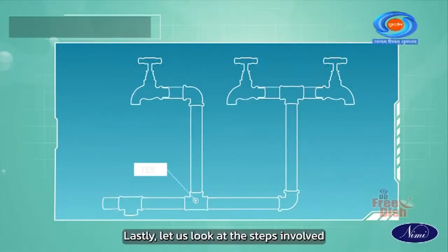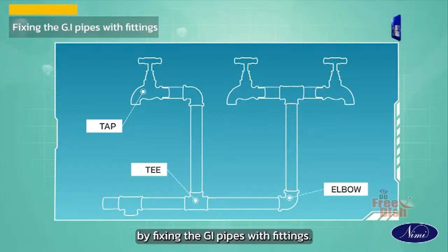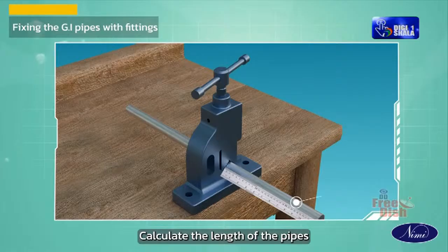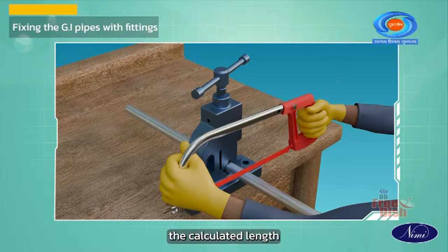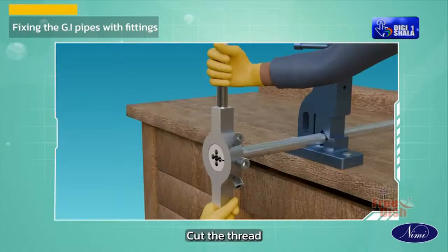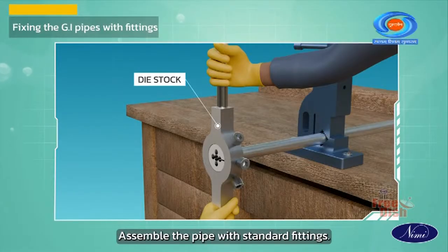Lastly, let us look at the steps involved in a simple pipeline connection by fixing the GI pipes with fittings as per the drawing. Calculate the length of the pipes required based on the drawing. Cut the pipes as per the calculated length using a pipe cutter or a hacksaw. Cut the thread at the end of the pipe using a die stock. Assemble the pipe with standard fittings.